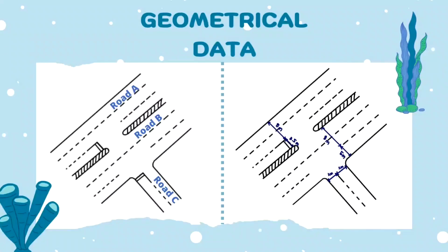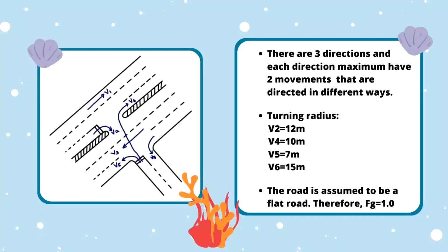In addition, we also determined the route width by using Google Maps. Next, we determined the route width for each lane. First, for route C, both lanes are 4 meters. The width of the two lanes for straight movement in routes A and B is 8 meters. The width of the left movement lane for direction A is 4.5 meters and for direction B is 5 meters.